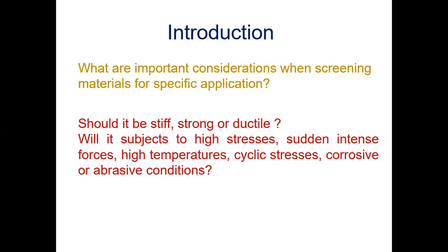What do you expect the selected material to have depending on your application? So you should think about, should it be stiff, or should it be strong, or ductile, or should all the properties be there, or like that, right? So with that shaft subjected to high stresses, sudden intense forces, high temperatures, cyclic stresses, corrosive conditions, whether it will be exposed. If it is exposed, your selected material can withstand those conditions or not, right?